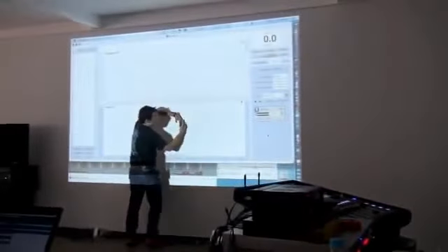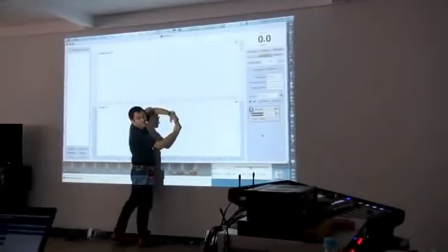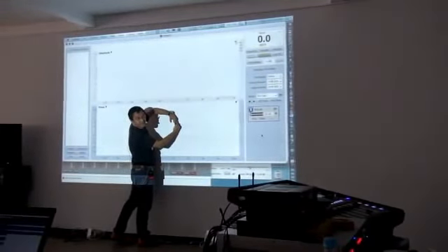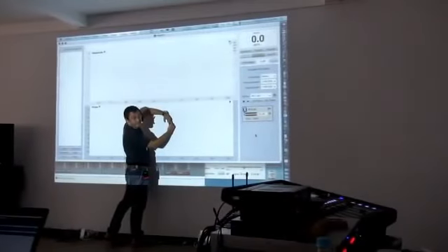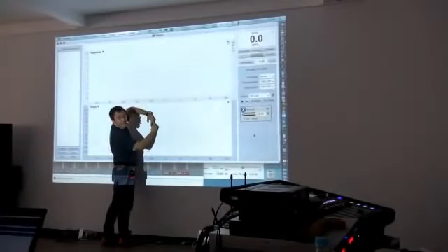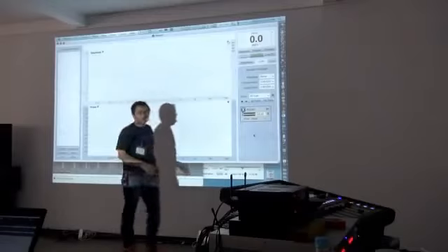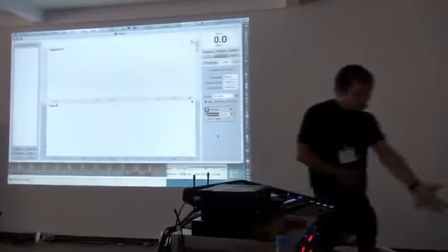1.25 milliseconds latency in the Lake allows a 96 dB filter at 1.6 kHz, or a 48 dB filter at 800 Hz, or a 24 dB filter at 400. The crossover point for floor monitors is between 800 and 1.8 kHz. With this option, he can make floor monitors for Barbra Streisand using his processors.